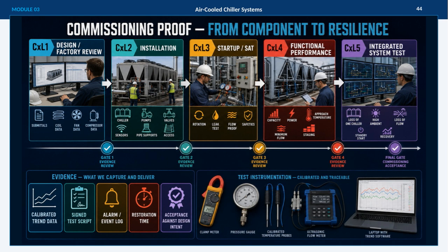Here, we apply a representative load, reconcile it with the measured duty, hold conditions until stable, and carefully record any uncertainty. In functional performance testing, we initiate one controlled failure to verify both automatic and operator responses, while checking residual capacity and temperature excursions. Restoration proof includes returning the system one controlled step at a time, confirming standby availability, closing overrides and alarms, and signing off on restoration.